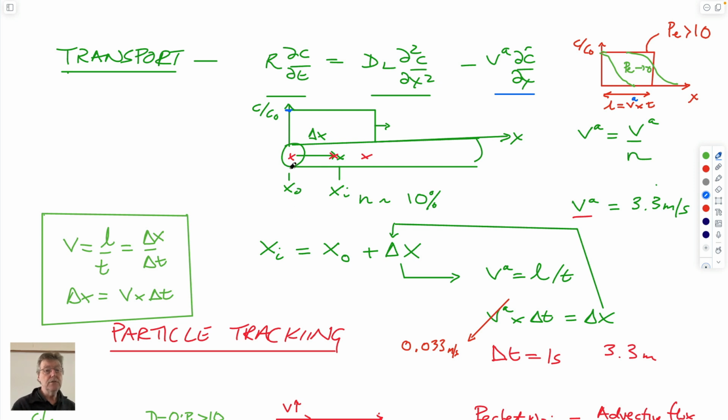And so the easiest way to do that is to just release a whole bunch of particles at this point, which flow downstream, carried by the water, and count in all the boxes that we have at these monitoring locations how many of these particles we have. And those you could think of as molecules of this component that is dissolved in water. The more particles you have, the more molecules you've had in that given volume of water, and therefore the higher the concentration. That's basically it.